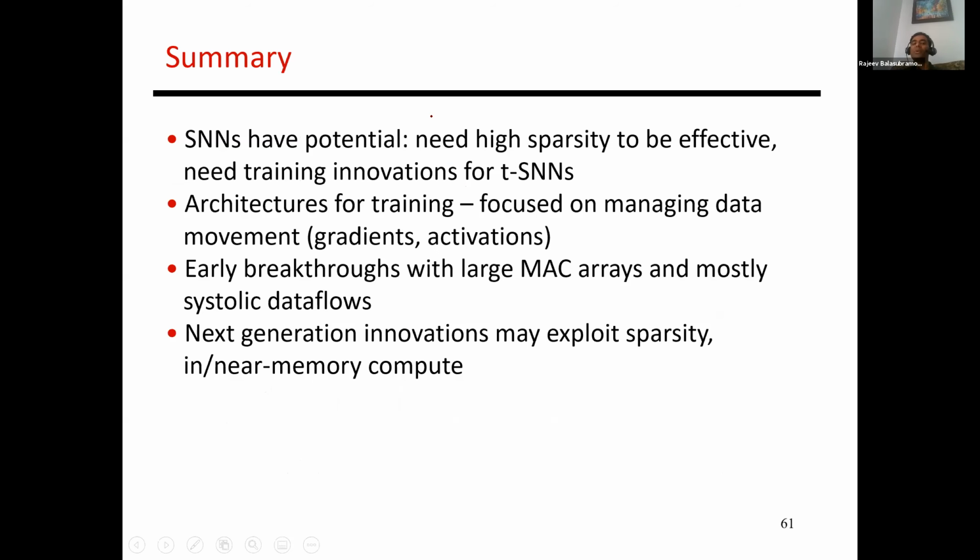All right, so this is my closing slide, closing slide for the entire lecture series as well, right? And so what we've learned in these 3 lectures is firstly that we've seen a big jump in machine learning hardware in these first few years, right? Even the commercial offerings are giving improvements of 100x, and a lot of that is just coming from customizing for deep networks, right? If you just put in a large number of multiply accumulate units, you can get high throughputs. Scaling helps. And even the networks are now trying to become smaller, right? And so we are also getting some help from the algorithms themselves.